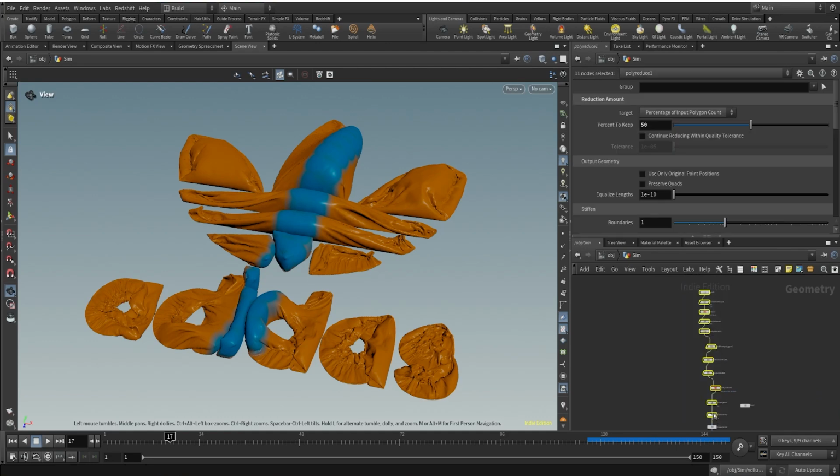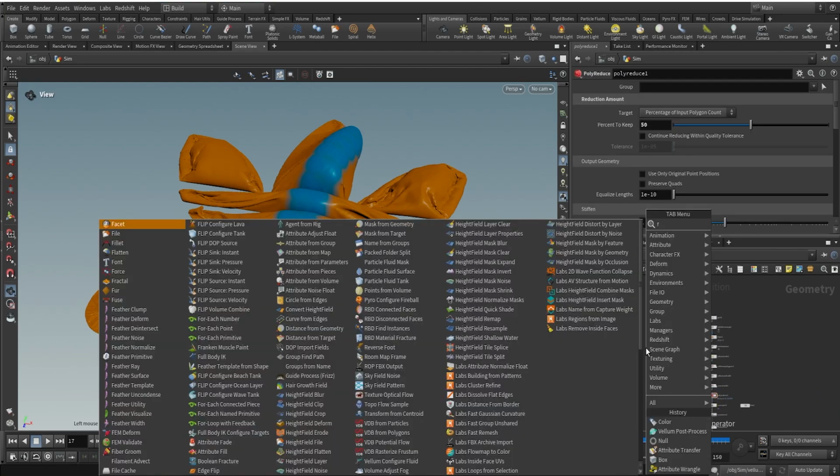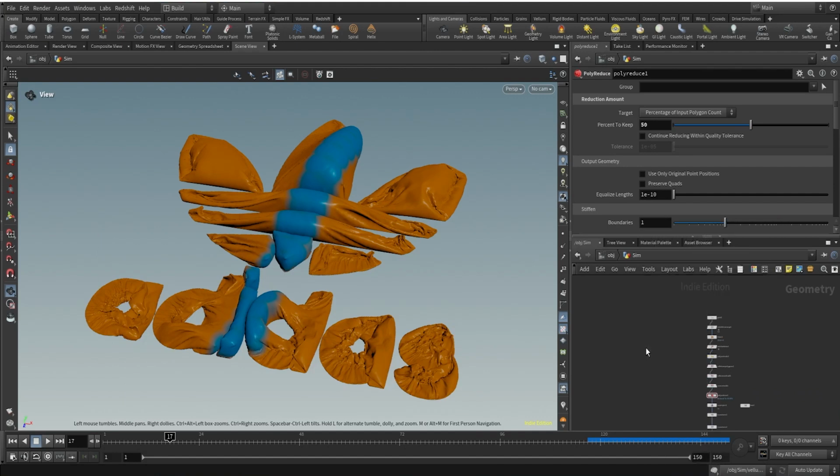Okay, and why are they useful? Because if we are simulating something as rigid inside of a Vellum solver, that specific Vellum rigid will be able to react with other Vellum properties. Like if we are creating Vellum cloth, then it will react with Vellum cloth, and if we are creating Vellum fluid, then that Vellum shape match rigid body that we are creating will be able to react with our Vellum fluid. So with the help of the Vellum rigid bodies, we'll be able to do that. Okay, so let's do that now.